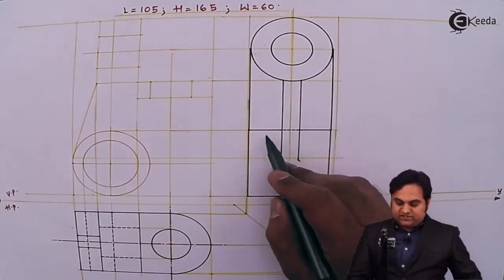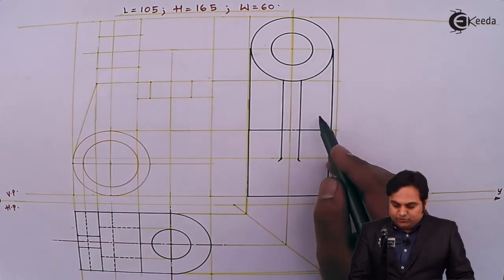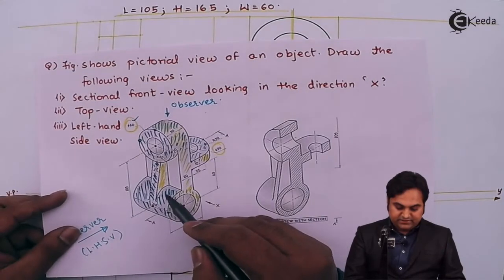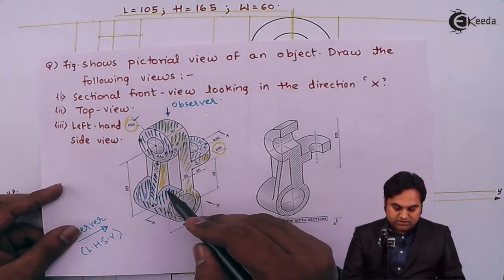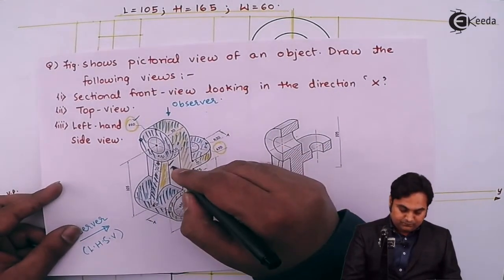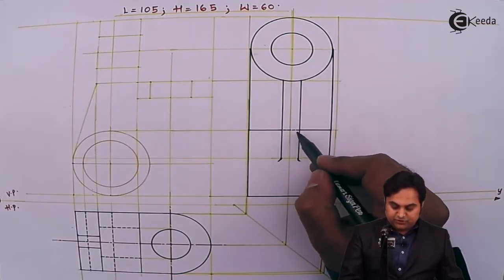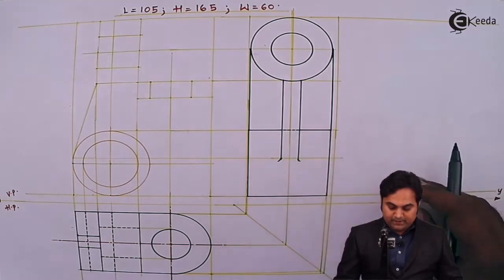And here as we see the change of plane, it indicates that both the surfaces are on different planes, and that we can make out here as this cylinder and the surface. Cylinder is ahead, this surface is behind. So there is dark line in between them, and this much portion goes inside the rib, so it is hidden.